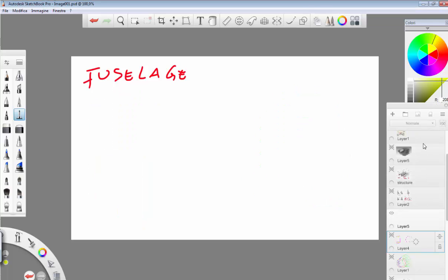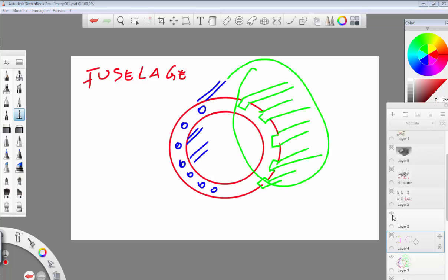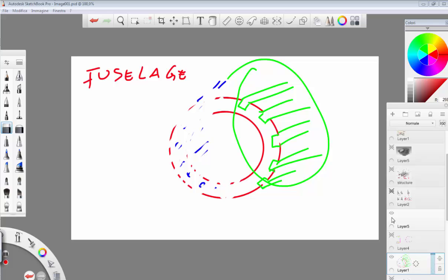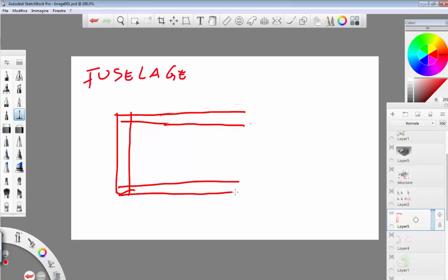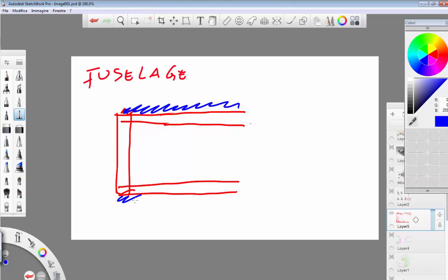So for our purpose, the best is to use this approach, which is what we see later. So in this case, you will have your former in this way. Oops, sorry. And in this way. So when you apply the mylar, twill, or any kind of other cover, it will be just glued to the stringer or longeron, so you will not have some bubbles or what else.